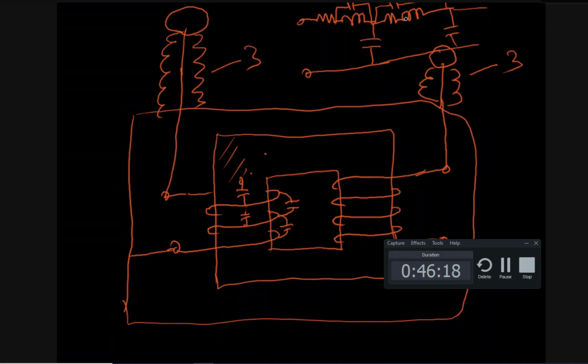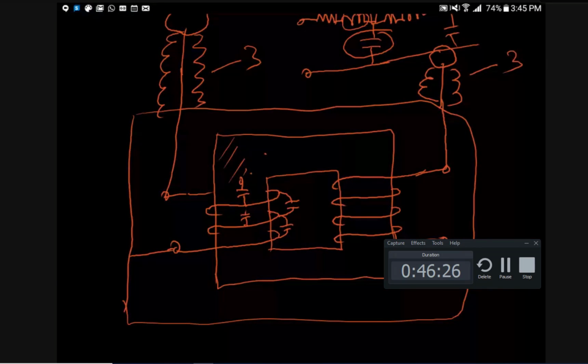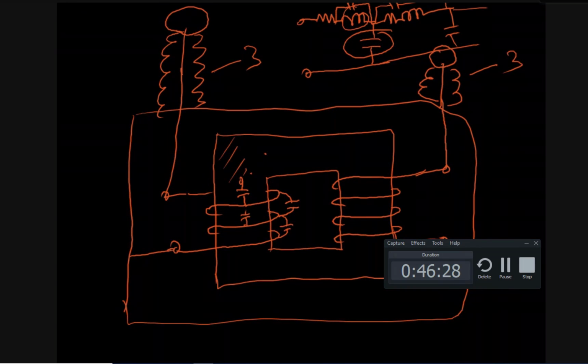Naturally, if there is damage in the winding, then the corresponding capacitance or inductance parameter will change. And when the capacitance or inductance parameter changes, obviously the network function will change. So this is how, by observing at the terminals, and I am not opening the transformer.